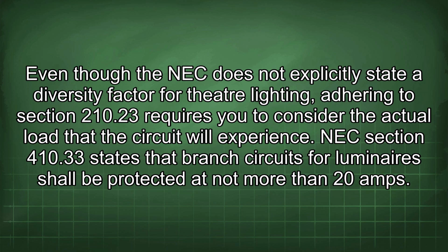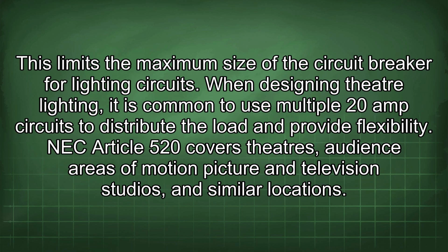NEC Section 410.33 states that branch circuits for luminaires shall be protected at not more than 20 amps. This limits the maximum size of the circuit breaker for lighting circuits. When designing theatre lighting, it is common to use multiple 20-amp circuits to distribute the load and provide flexibility.